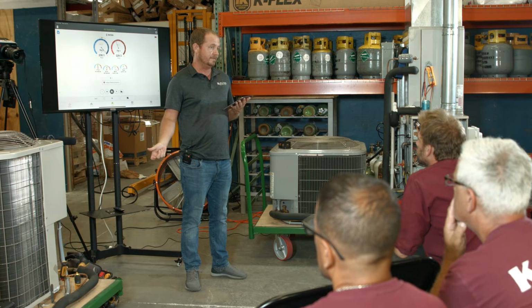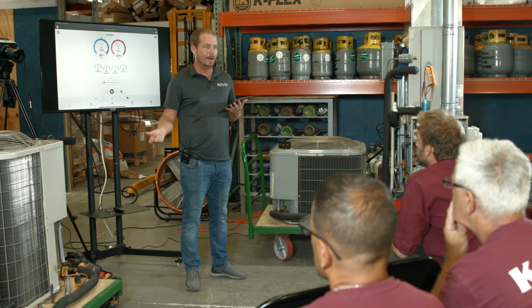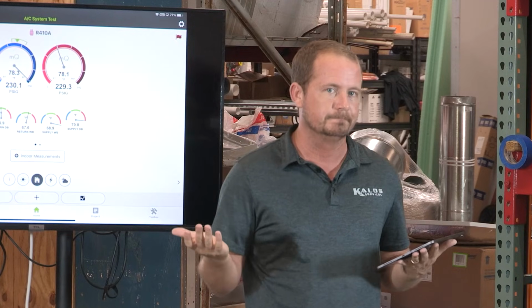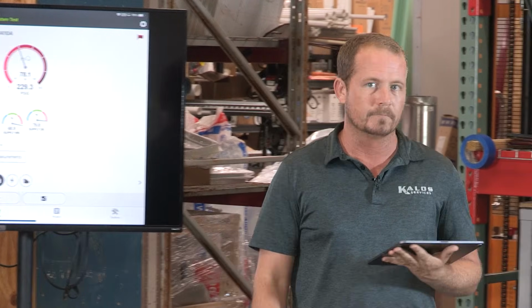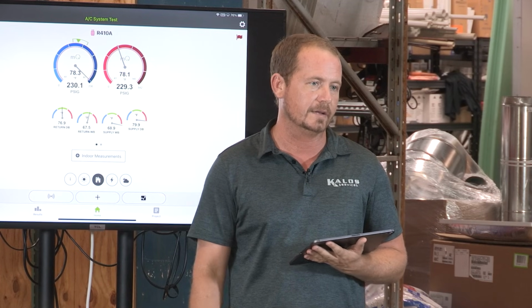So an experienced technician will go up to a system, grab a suction line, and feel that it is especially cold, and you're looking for airflow. It really is kind of that simple. Now, I'm not telling you that's how you do it. You don't just walk up and grab a suction line. But if a suction line is especially cold, probably airflow or low load, in this case being an air conditioning system, that would be a house that's too cold, right? Somebody set the thermostat way down and let it run. But under normal operating conditions, having a suction line below 50 degrees, more often than not, is going to be an indication of low airflow.